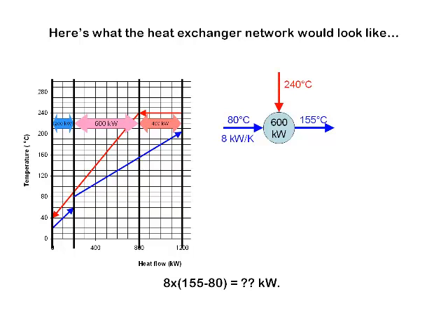Our hot stream is the other stream that's coming into that heat exchanger. It's coming in at 240 degrees C. It has a flowing heat capacity of 4 kilowatts per Kelvin. It comes out at 90 degrees C. So here the calculation is 4 times 240 minus 90. 240 minus 90 is 150. 150 times 4 is 600 again. Of course it is. 600. That's the amount of heat transfer that's going on in that heat exchanger.